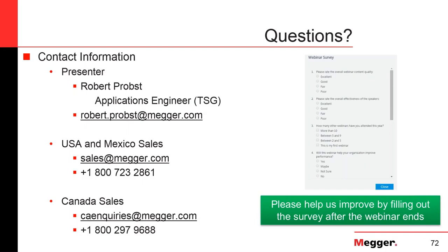So actually, in the medium voltage world, primary injection is also used. It's not just for the low voltage applications. I just had to focus the presentation because of the time restrictions. But it is also a very common method in the medium voltage world to test the entire system: CT, relay, circuit breaker. You want to add to that, John?